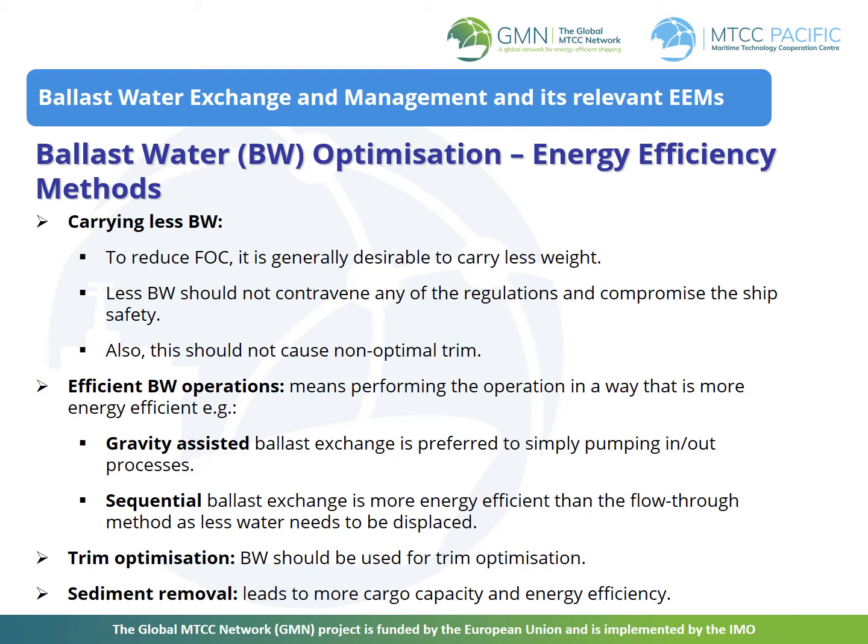Thus, there is an optimum ballast condition that needs to be achieved through cargo planning as well as voyage planning. Optimizing the ballast levels for energy efficiency within the framework of ship's stability, steering ability, and optimum trim can be regarded as an energy efficient measure.